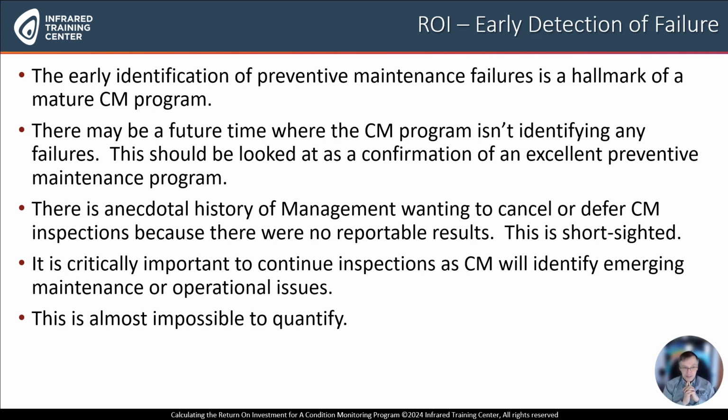This is very short-sighted. If you're not finding something with your program, and you've got all the technologies out there, the infrared thermography, the lubrication, the vibration, the motor testing, etc., that is confirmation that you have an excellent preventive maintenance program. And the condition monitoring program will tell you right when that preventive maintenance program starts to go sideways.